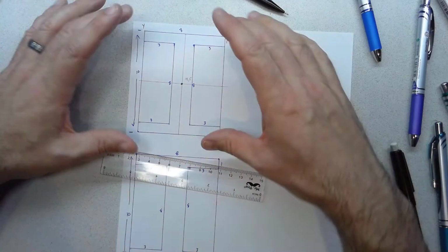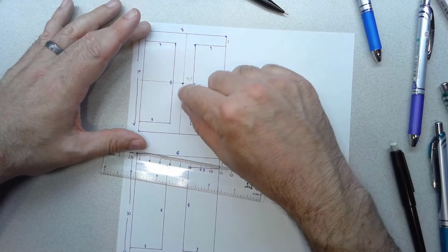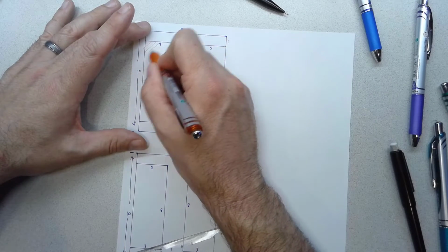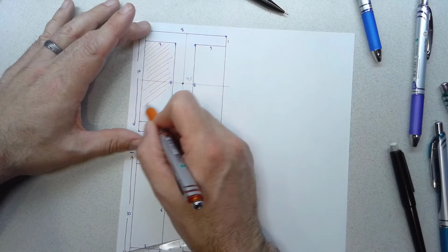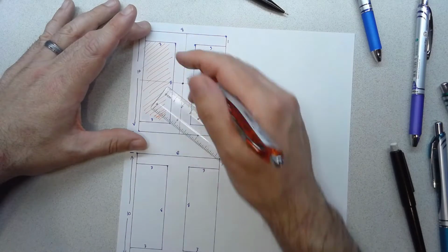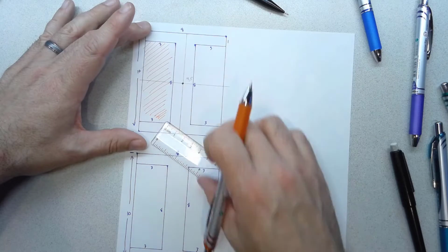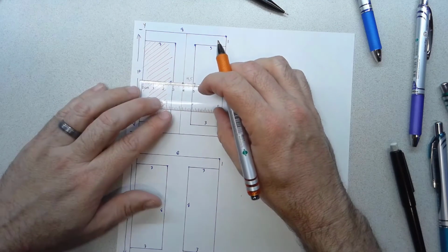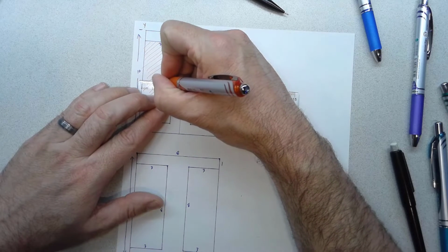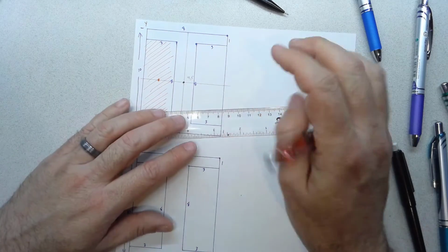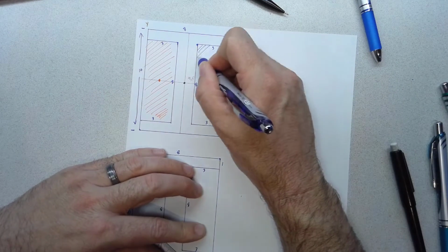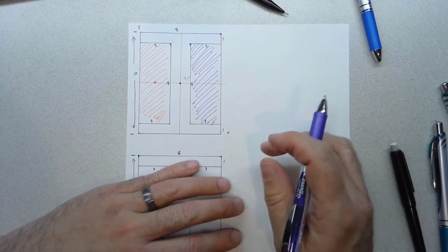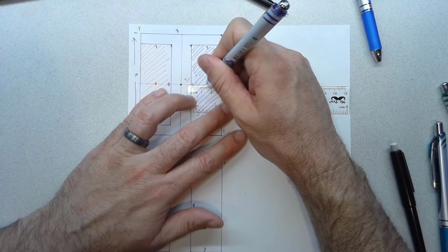Okay, then let's look at some other pieces. We said the whole rectangle is one piece that we care about, so we found the centroid of that. And then what we talked about is we're going to subtract some areas. So the first area we're going to cut away from this rectangle would be this section on the left side. And its centroid would be along that same axis, right? We have symmetry about that axis here, but now the centroid's no longer over in the middle, right? We're looking at the centroid of just this orange rectangle, so its center would be 1.5 over, since this distance is 3. So the centroid of that one is going to be right there. Okay, then the other area that we're going to subtract would be this part over here, and same thing for it. Its centroid is easy to find.